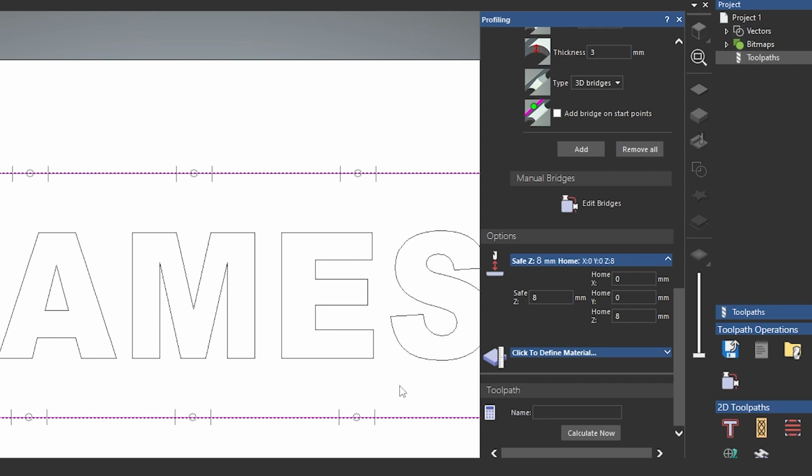For example, if you are using clamps to hold down your material and your clamps are 5mm thick, then the absolute minimum number you would want this to be is 6mm to guarantee that it cleared those clamps. And that's essentially the easiest way to think about it, whereas the absolute minimum height you want your bit to raise above to make sure that it doesn't hit anything. I usually leave it at 8 or sometimes go up to 10 if I'm using particularly awkward clamps, but for now we'll leave this at 8mm.